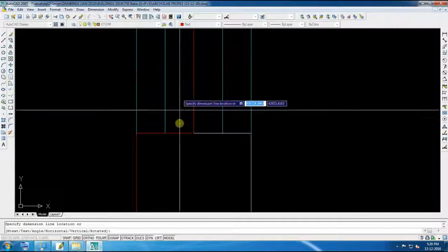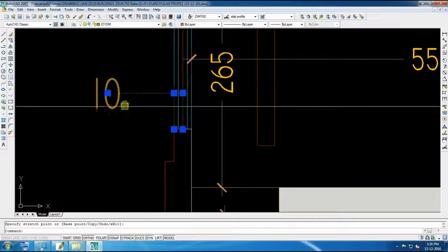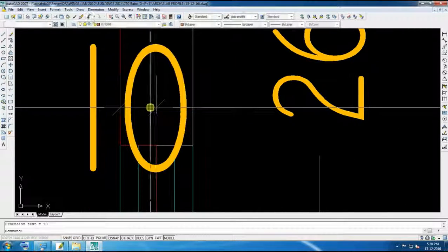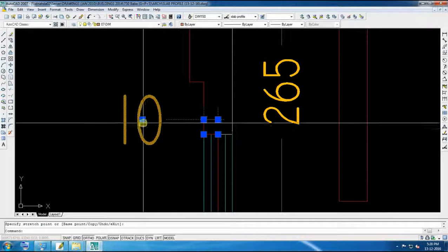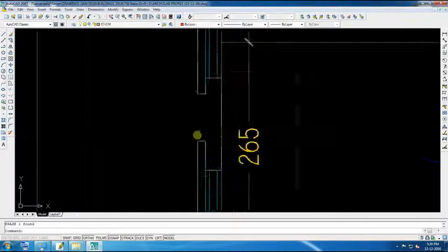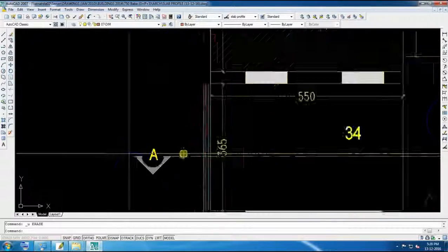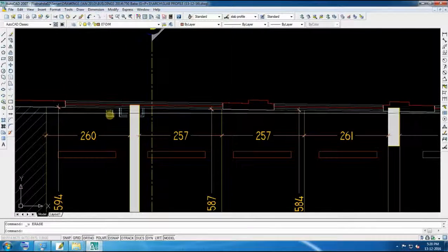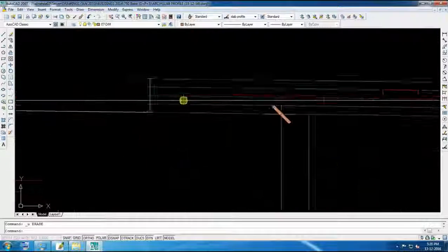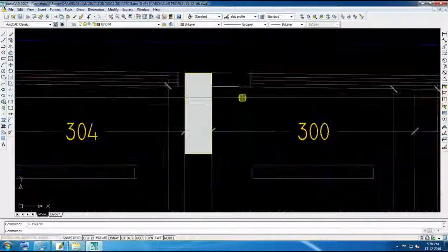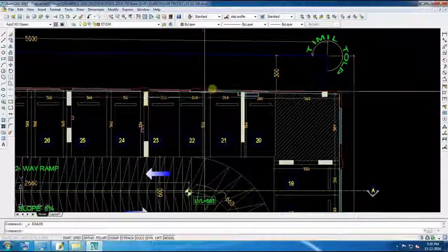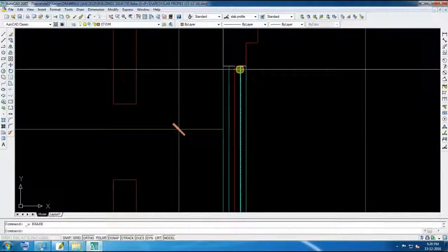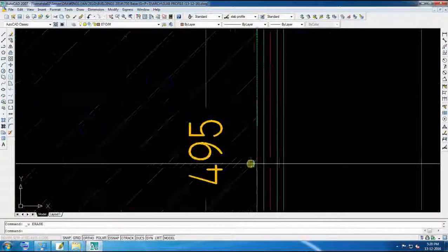For fixing details as per elevation, wherever our wall is reflecting, we adjusted that part. We can see 10 cm everywhere here. So I made the polyline as per this, everywhere it comes. A little bit, 0.005, is not so important, but a 5 cm, 10 cm or 8 inch difference will become a big problem. This is structural work. A slab profile is not easy and not very difficult, but it needs experience.